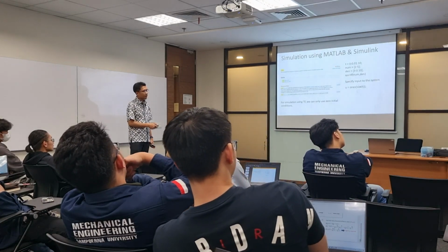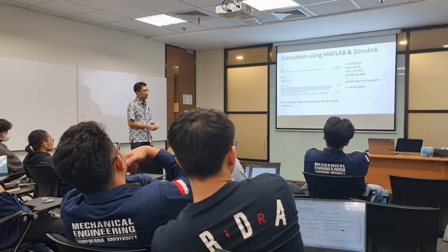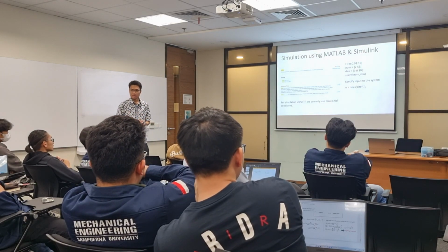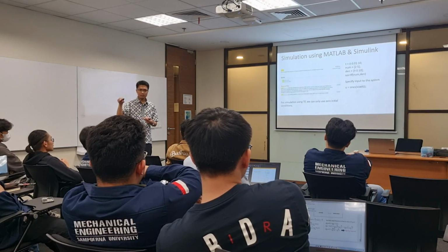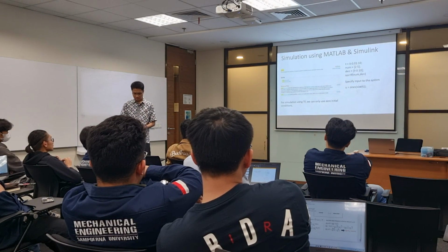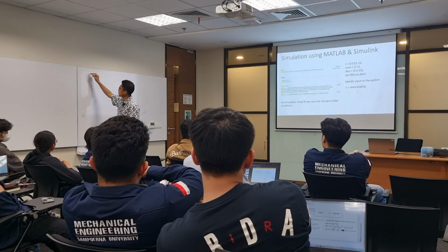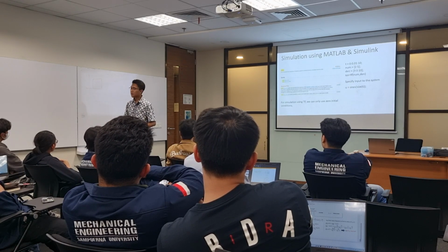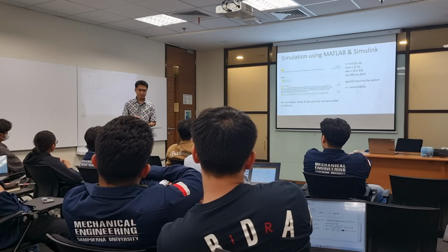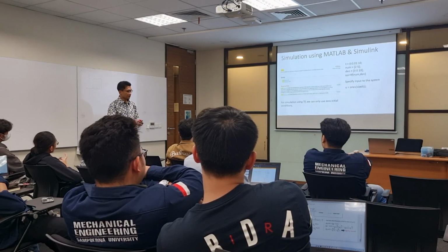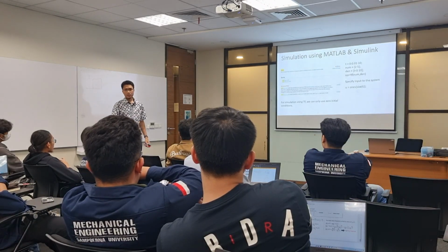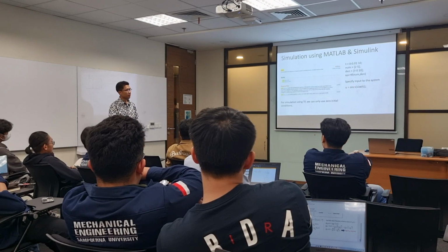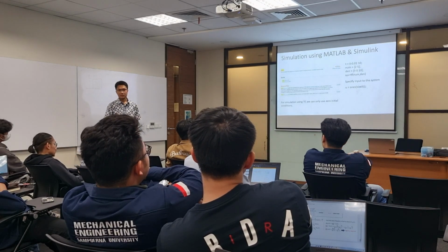So how do we specify input to the system? You just define any kind of input. Let it be a sinusoid, step input, or an indicator function like this one. You just have to specify it. In this case, let us define a unit step function. To define a unit step function, we just write ones(size(t)).